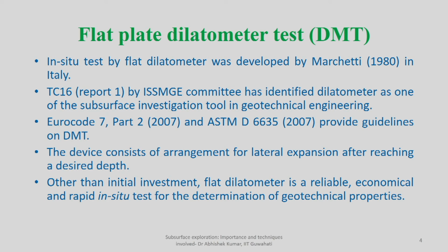Other than the initial investment, the flat dilatometer is a reliable, economical and rapid in situ test for the determination of geotechnical properties. Other than the initial investment, which is particularly for the purchase of the equipment, this method can provide you very reliable and robust information, and numerous parameters you can determine once you do this kind of test at the site of interest. It is also more economical because you are going for continuous recording, just like the CPT test.